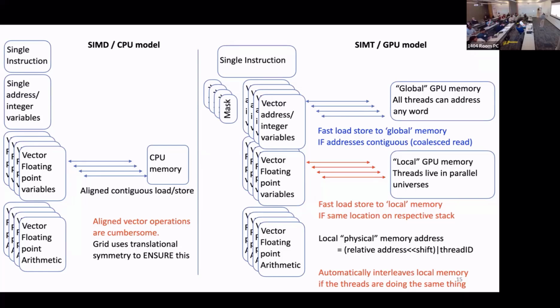Otherwise, if they're all accessing different addresses to each other, and their address registers are independent here, so they can all be different addresses in principle, depending on how you write your program. It's data dependent. So the GPU will look at the data, and essentially say, right, I have to fetch the first guy's address. Can anyone else use this? And if they do, they go, oh great, we're done, right? If they all have different addresses, then we'll have to fetch however many different addresses there are amongst all of these registers before it completes that load instruction.